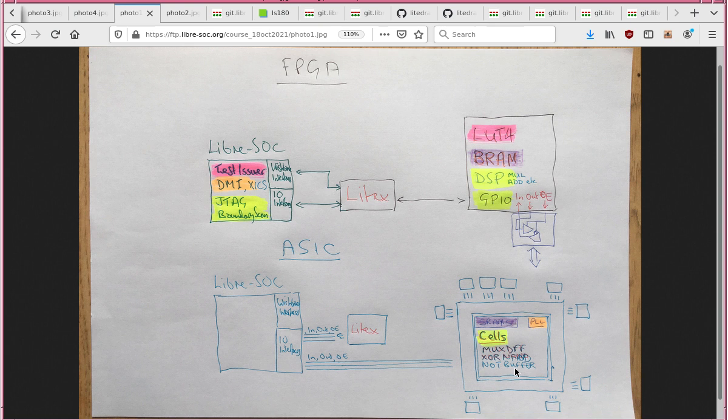We had quite a bit of a fight with Yosys over getting it to do that, because if we had not marked the 4K SRAM as a black box cell, then what Yosys would have done was it would have gone, oh, this 4K SRAM is an SRAM, I don't understand memory cells, so I'm going to create a massive set of flip-flops for you, which would have been about 10 times bigger than the actual chip.